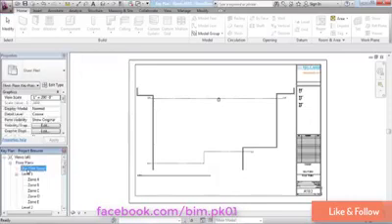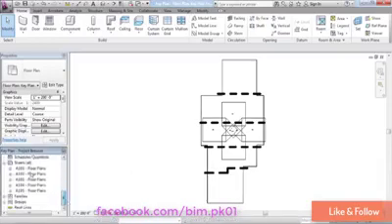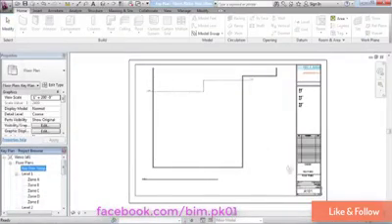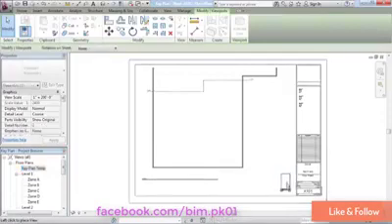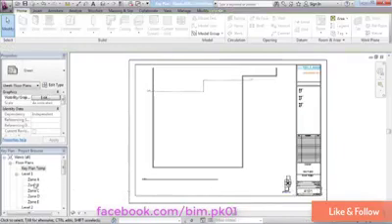So to get myself started, I have created a temporary key plan view here that I called Key Plan Temp, and this is set at 1 to 200 scale. Now if I went to the floor plan and actually dragged this view on here, this would be the approach that a lot of folks initially want to try here. You'll see that it's about the right size for a key plan, but again, the trouble is I can't add that to more than one view.